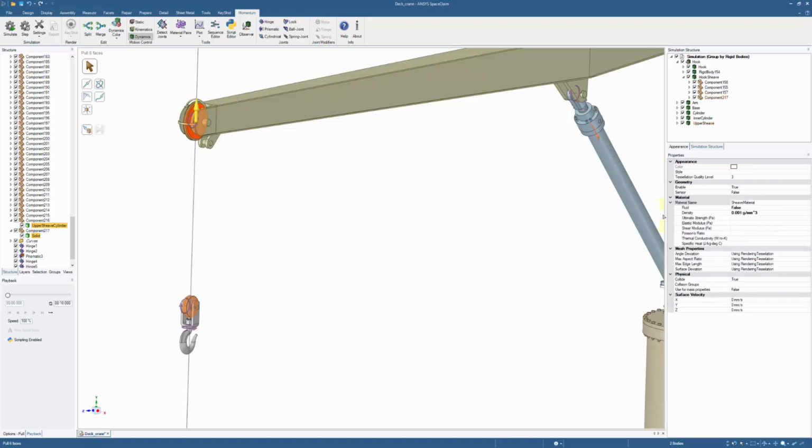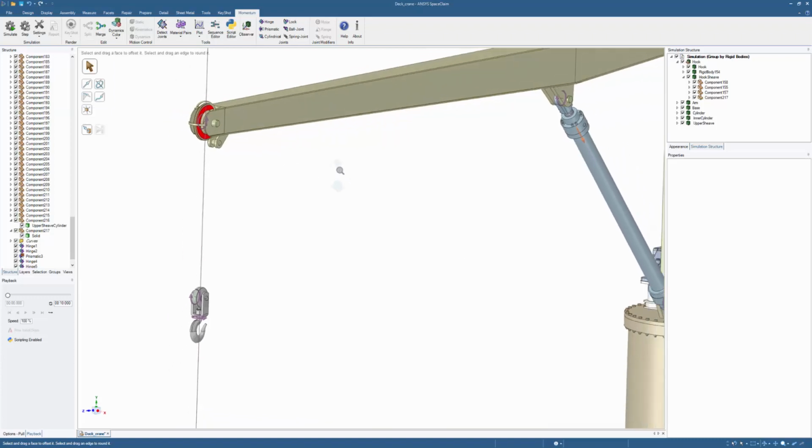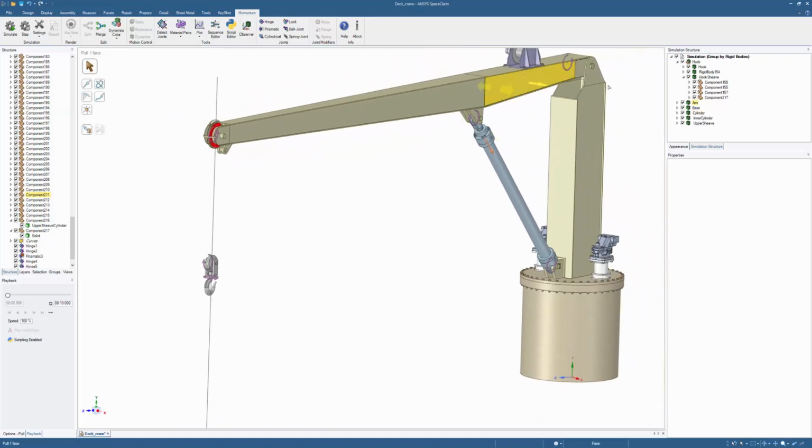That will generate a new material which will be assigned to these cylinder shapes. We also set the simulation frequency to be the same that we're going to use inside of Unity. And the reason for that is that Algoryx Momentum will calculate damping for constraints depending on the simulation frequency.